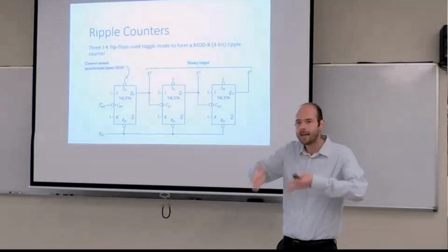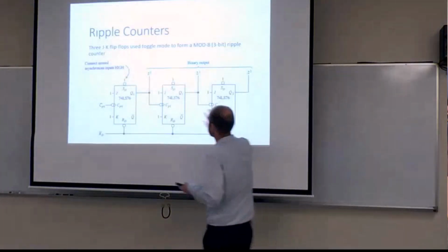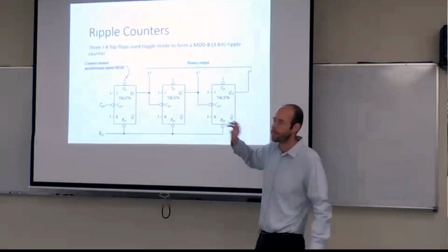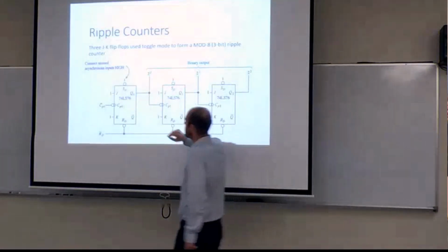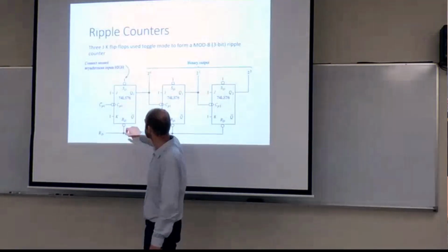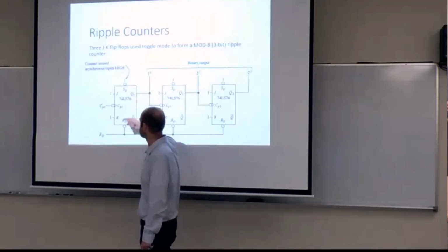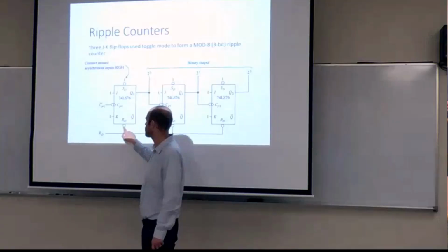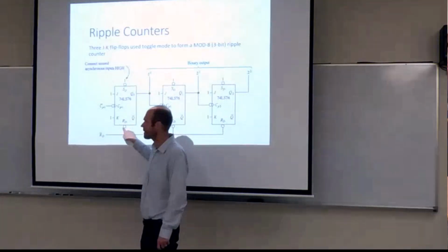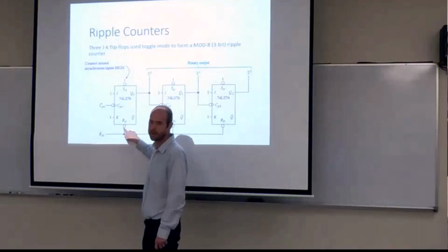At the flip-flop device level, it would look like this. These are 3 JK flip-flops. We have a clock signal coming into our first one. Here are our asynchronous set and reset. Because we have this bubble on the input, what does that imply about that particular input?